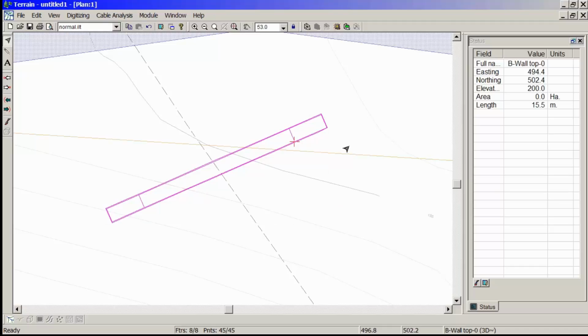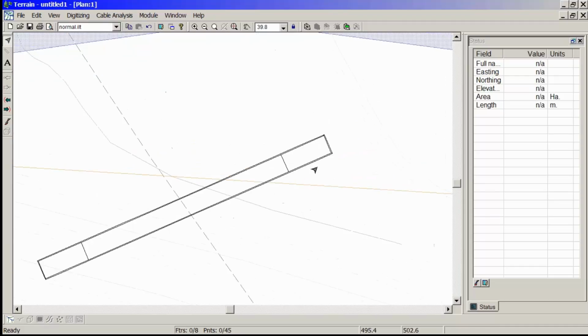Next step is, I'm going to have the ballast wall sitting on top of a riprap fill, make it a little bit more stable. I got to click the base of the wall, or select the base of the wall, and then grade it down to the ground. Just have to figure out which way I'm going to grade. I got to grade to the right.